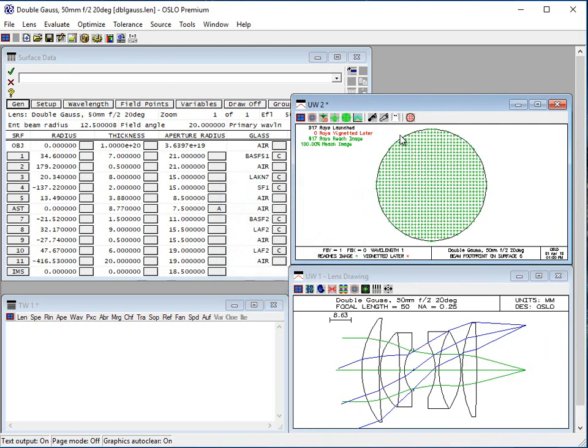Now you can see the rays are spaced nicely in the pupil, and the sampling is very good, as well as it fills the entire pupil stop correctly. So we are launching at the stop in the system, and it is filling it correctly, which is what we're really doing with this. Of course, we've lost a little bit of speed. You can't see it in what I'm doing right now, but if you're doing something that's heavily ray trace intensive, then that speed differential might start being noticeable.